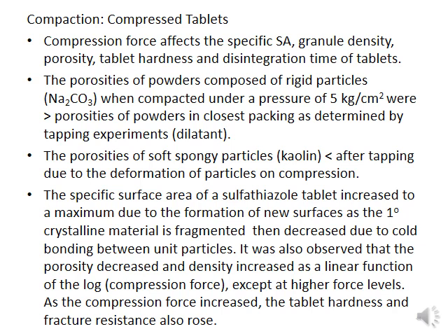Compression force affects surface area, granule density, porosity, tablet hardness, and disintegration. Previous investigators found that when powders were compacted under a pressure of 5 kilograms per square centimeter, the porosities of powders composed of rigid particles such as sodium carbonate were higher than the porosities of powder in closest packing as determined by tapping experiment.